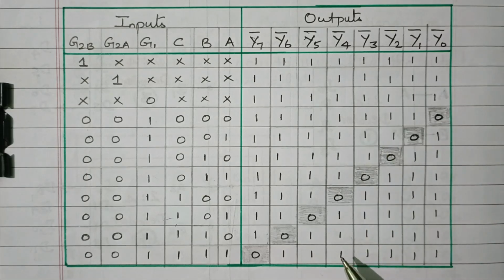So in this video we discussed the 3 to 8 decoder. The number is 74x138, right? Having 3 inputs and 8 different outputs. In that, the outputs are inverted outputs, so we are getting only one 0 and all the other outputs are 1.